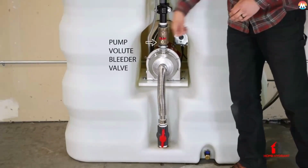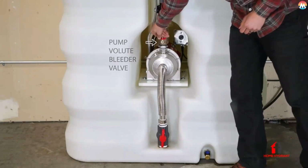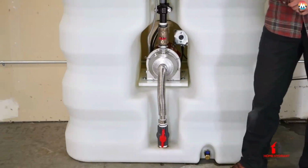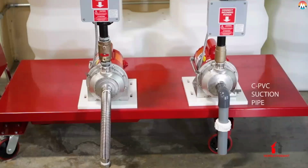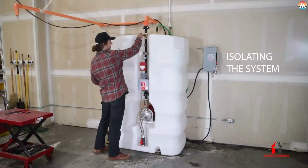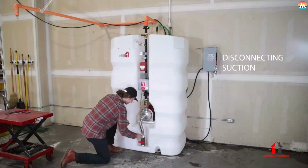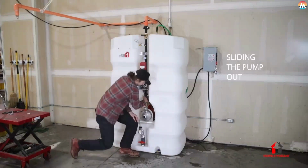Next, we integrated a pump volute bleeder valve and a riser drain port separated by the seat of the check valve. So bleeding the air is as easy as opening the valve. We redesigned our suction system by replacing the old CPVC suction pipe with a stainless steel flexible hose. So if the pump ever needs to be removed, it's as easy as isolating the system, turning off power, disconnecting the suction, breaking the grooved coupling loose, and sliding the pump out.